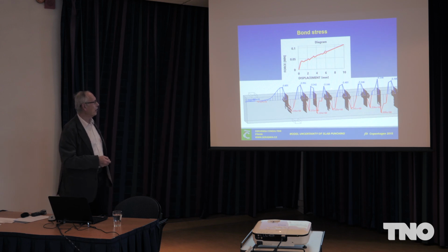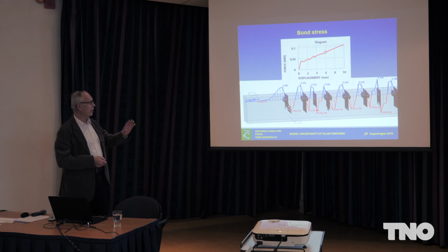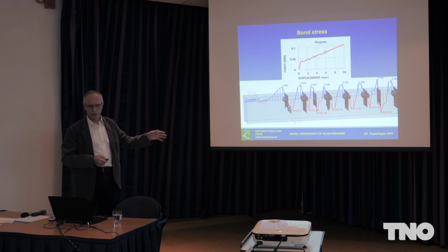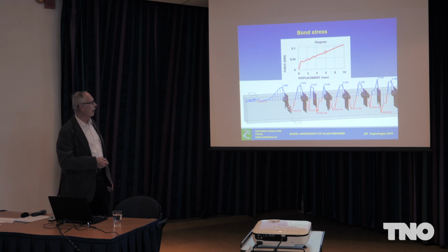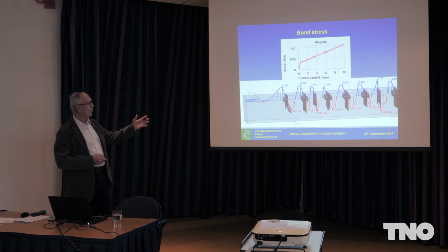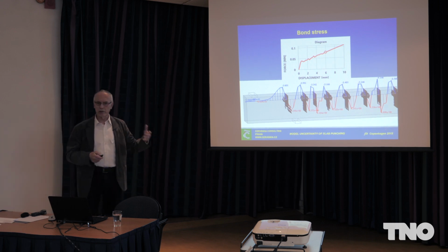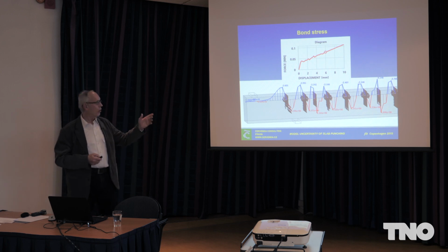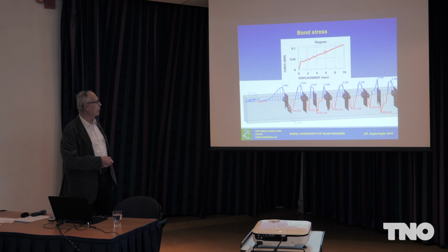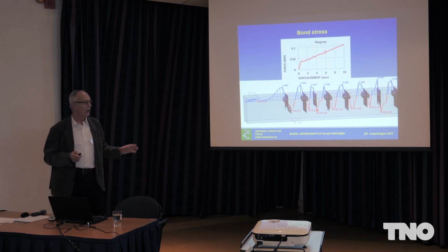And you see that we have cracks. We can determine crack because it is localized strain. And we have also bond distribution here, very nice. So we have been comparing this, of course, with the code model, where the only difference is that they assume constant bond here, and they assume nothing about crack width. They just transfer the deformations along the bond, and that is the crack width. So